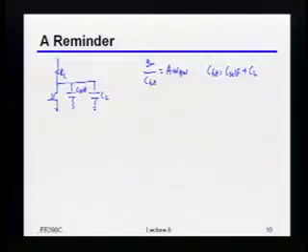Nothing magic there. Okay, so sometimes when people first look at this, they say, well, this is kind of annoying because the self-loading capacitance is proportional to the size of your transistor, right? And so it seems like there's some iterative loop you have to do to solve this. It turns out you can just directly write the equation and solve it. Okay, so I'm just going to do a couple of steps to show you how to do that.